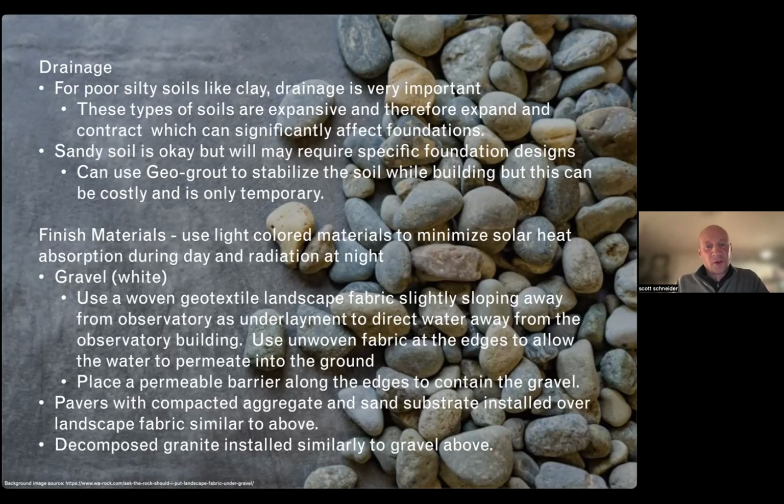On some sites where the soil is really poor, you can remove that soil and truck in a better structural type of soil. It has to be compacted, and that can take time, and it obviously comes with a hefty price tag. Sandy soil can be okay if you're on a flat site.